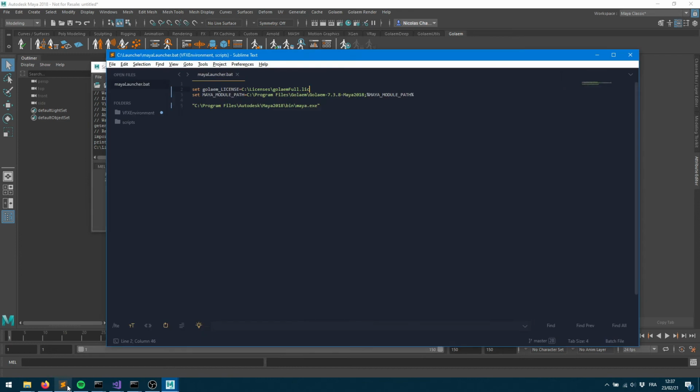So maybe let's also play with something more advanced. Let's say you've got multiple versions of Maya, and you may notice that if you load Maya 2020 or Maya 2018, you'll have to change the path in multiple locations. So what you can do is define something called, maybe, MAYA_VERSION, and we're going to assign the value 2018.